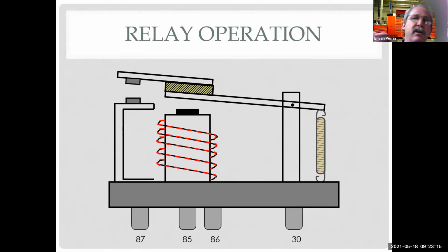On the other hand, if I didn't use a relay and I just said, you know what, I want to control it with just a switch, now I need to run a wire, which I could still fuse, all the way into the car to a bigger switch, and run that switch all the way back out to turn them on. So now I've got a lot more hot wires going. And since everything is surrounded by metal, that's more things that could rub through, arc and blow the fuse.